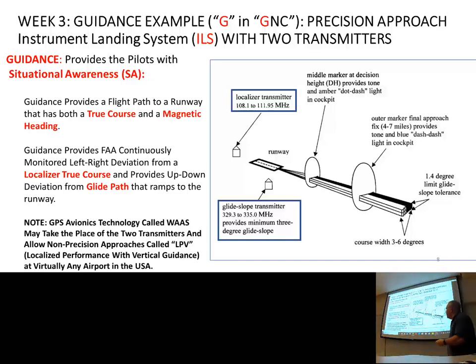The satellites from GPS have changed what we wanted to do, and it's taken a decade or so to infiltrate the pilot community. What the GPS global satellite system does is they have something called wide area augmentation. This wide area augmentation takes the place of these transmitters. They're extra satellites in space that give you a correction to GPS. So a pilot flying with GPS WAAS has about 1 meter accuracy.